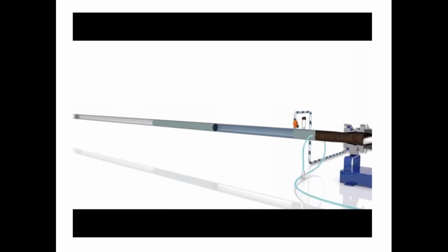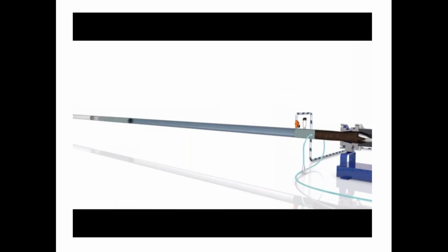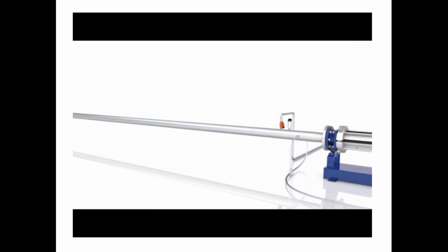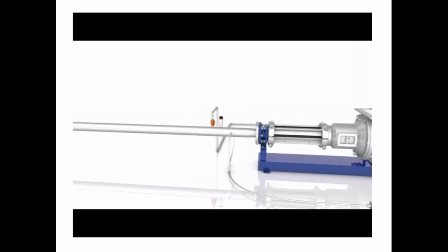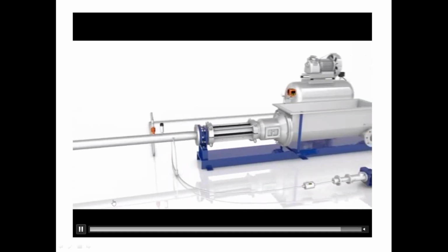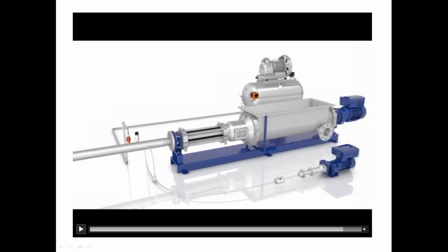In the past, to move something as thick as a 30 or 40% solid, long distances, you would need a gigantic pump. What Seepex has done here is utilize a single stage progressive cavity pump, a complete package system, including an air compressor and a small polymer chemical metering pump to inject a nice lining of polymer. You have the split stator option for pump readjustability, a laser level control to change the speeds, and a hopper with a self-cleaning ribbon auger.